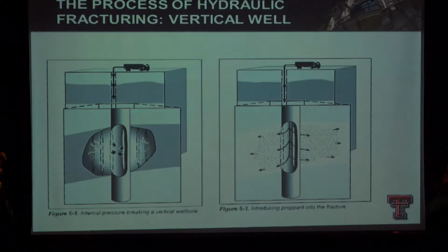So again, fracturing. So this is where I get to use my visuals a little bit. So you see here in the first well, these are conventional wells that we've been hydraulic fracturing since the 1940s. We pump fluids at high pressures, water, mixed with sand to create a crack, and then we follow that water with sand to fill the crack with the sand particles we call proppant.